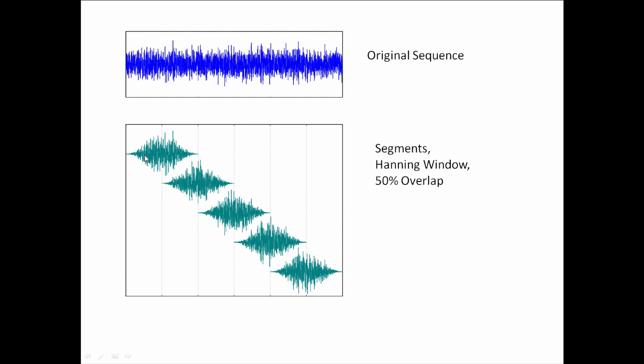Our next step would then be to take a PSD of each individual segment, and the final, overall PSD is just going to be the average of the 5 individual PSDs. Since it's RMS and G squared values, we can average the PSD G squared per Hertz values. And that's how we do vibration processing in terms of calculating power spectral density functions, particularly for shaker table testing, and in other contexts as well.